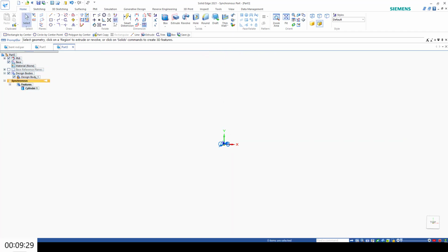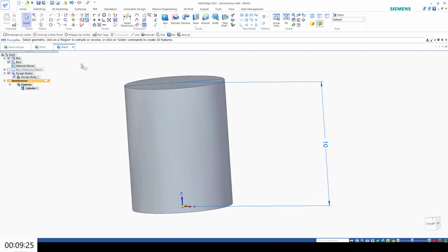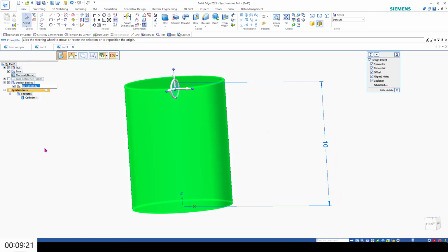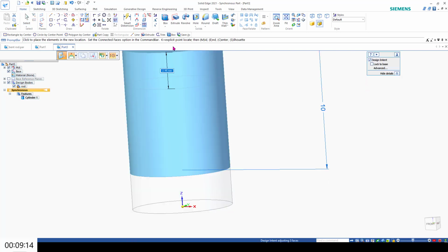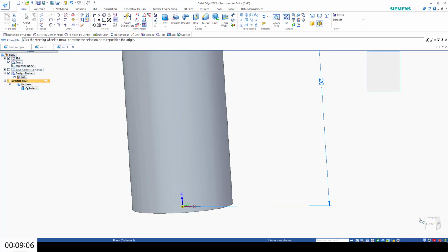You know what? I think that's just a little bit too low. Maybe I'll make it a little larger. So I'm going to select Design Body 1, rename it as Rod, and then I'm going to just add a little bit extra more height. Oh, Design Body selected. Let's grab the top surface, and there we go. Type in 10, and there we have it. Now it's 20mm high.